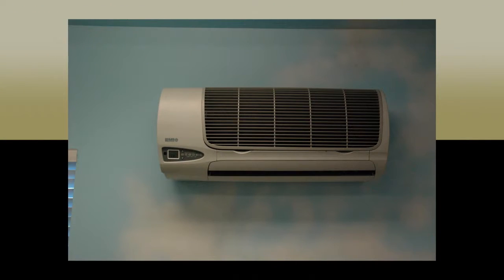The air conditioning unit is located on the wall above the anesthesia cart and is controlled by a remote placed by the light switch on the north wall. This must be turned on for each surgery and shut down at the end of each day. This helps us remain a negative pressure within the room.